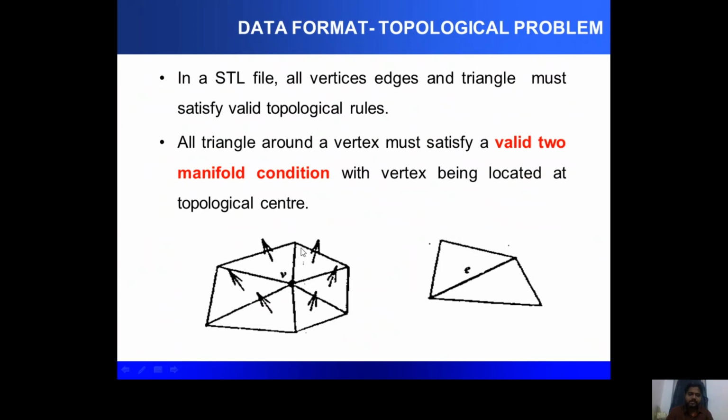In that case, the STL file may not generate the triangle, or it may generate multiple triangles which get overlapped. And this problem is because of topology. Most of the additive manufacturing processes we use are for very complex components, and in certain cases we will be doing reverse engineering. So if it is a general CAD model, there is no issue. You may have very simple shapes. But if it is a complex CAD model, I'll show in a video with a complex model.